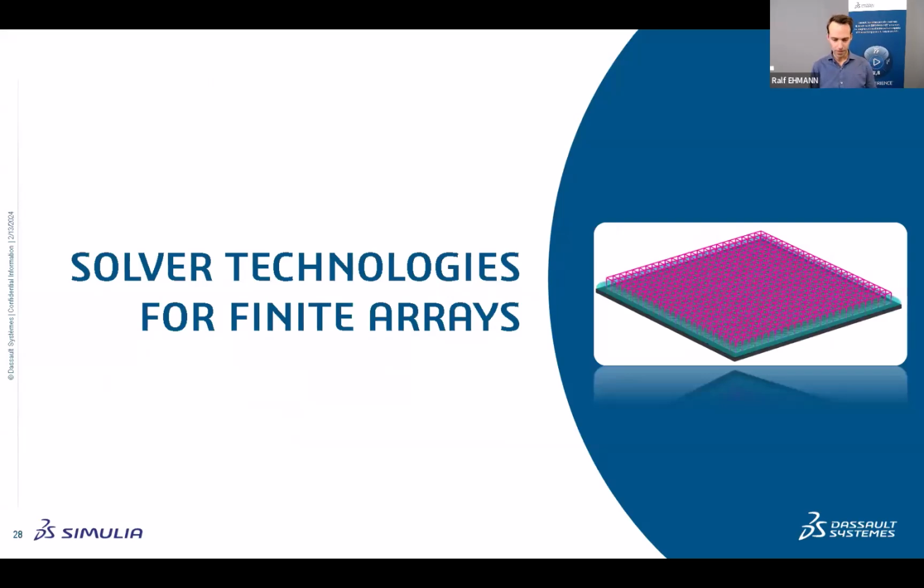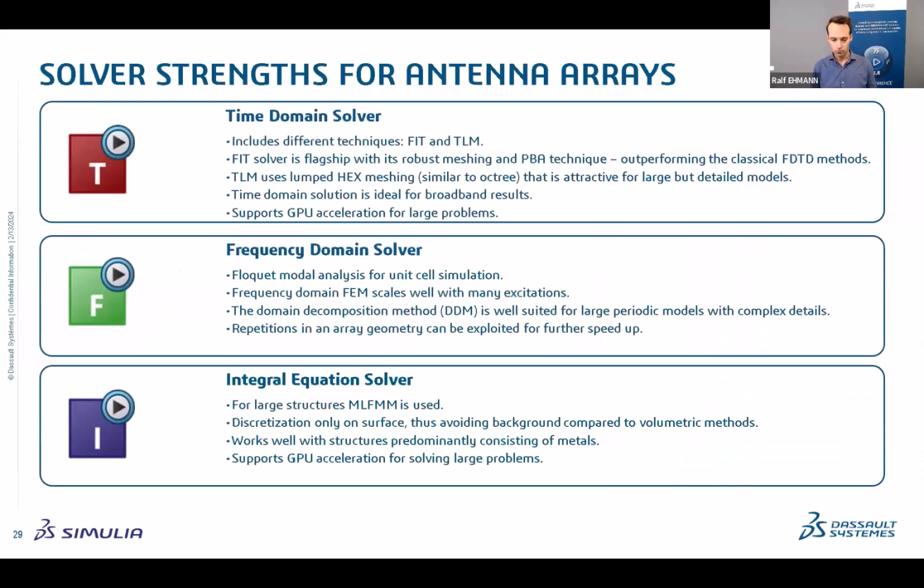So this brings me then to the solver technology, because it's one thing to automate the setup, modeling, everything. It's another thing to actually solve these really large problems. And as you know, CST Studio Suite has many different high-frequency solvers: time domain, frequency domain, and integral equation. When it comes to time domain solver, it has 2 different methods. One is the finite integration technique, or FIT, which is really our flagship solver, and it's very robust with a PBA technique that it uses.